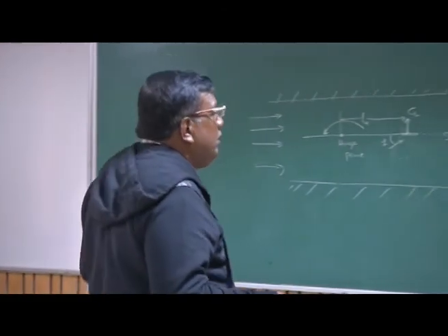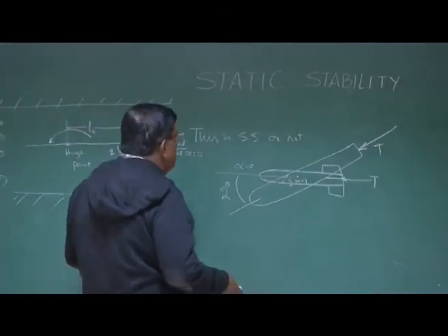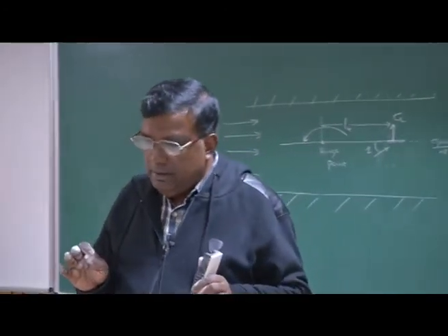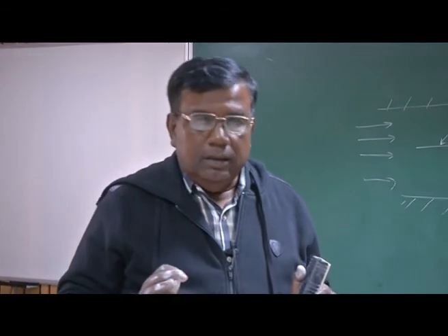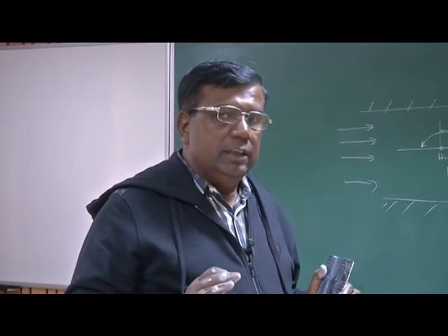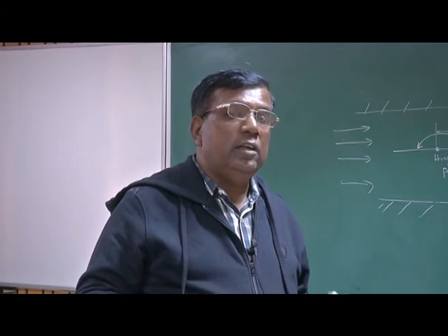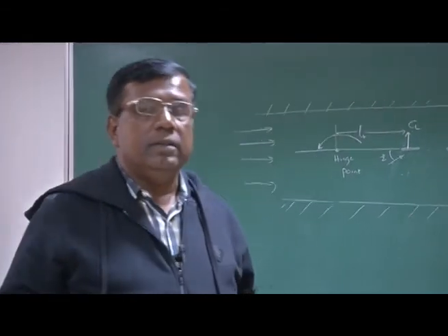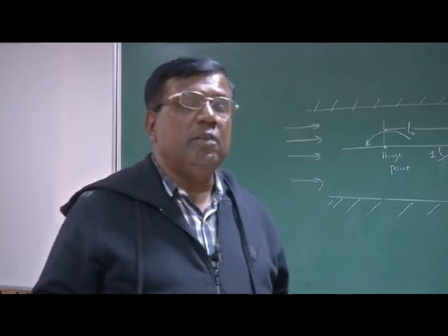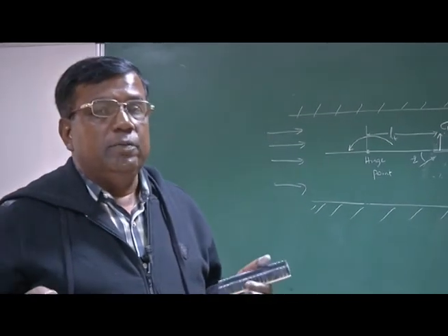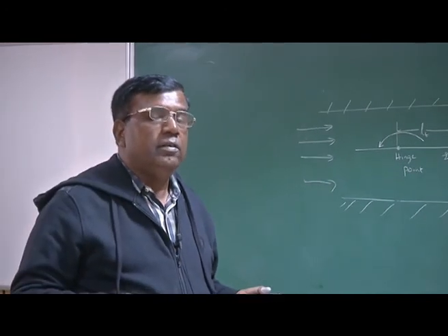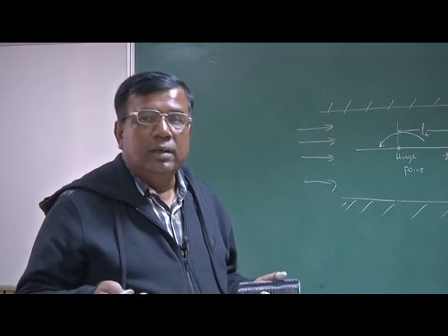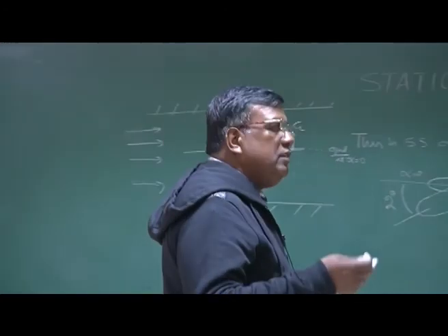That is why it is important, when you talk about stability, to ask how much stability. As far as static stability is concerned, it talks only about the initial tendency, but it has a larger influence on sensitivity, performance, and dispersion vis-a-vis wind. So it is very, very important. We should also clearly know how much static stability we want. And our lecture will address this question.